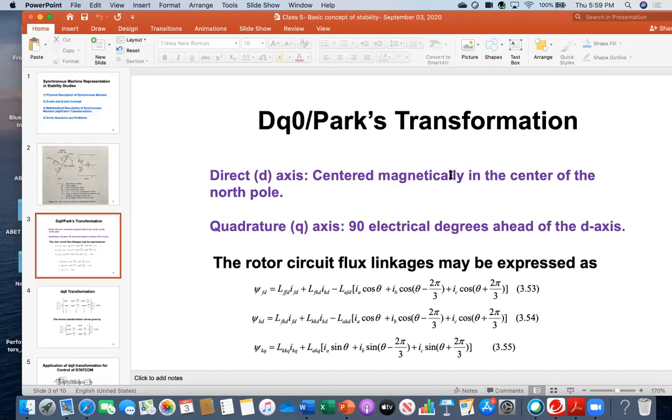This means if you have a time domain AC circuit, first you convert into the Laplace or frequency domain. What is the goal of that? That will be a function of the symbol S only. And then at the end, again you convert back into the time domain. That is what you do, and that is the beauty or essence of the Laplace transformation.